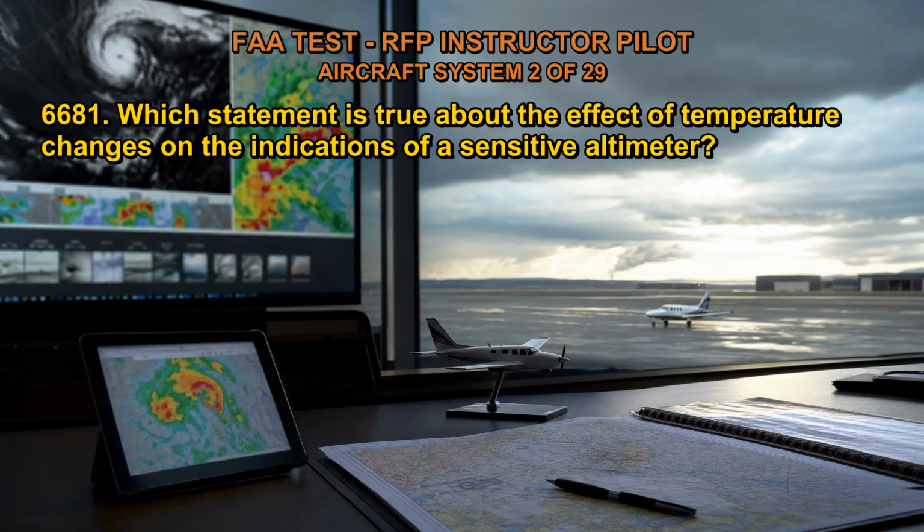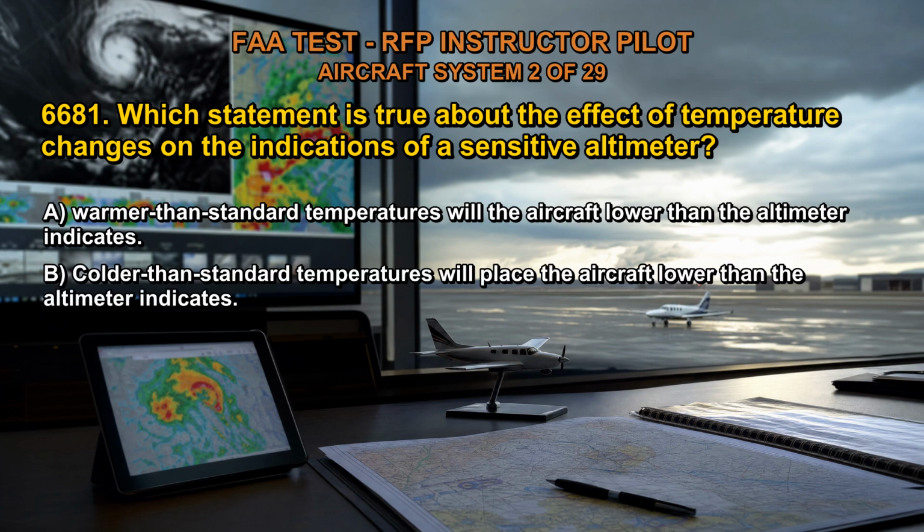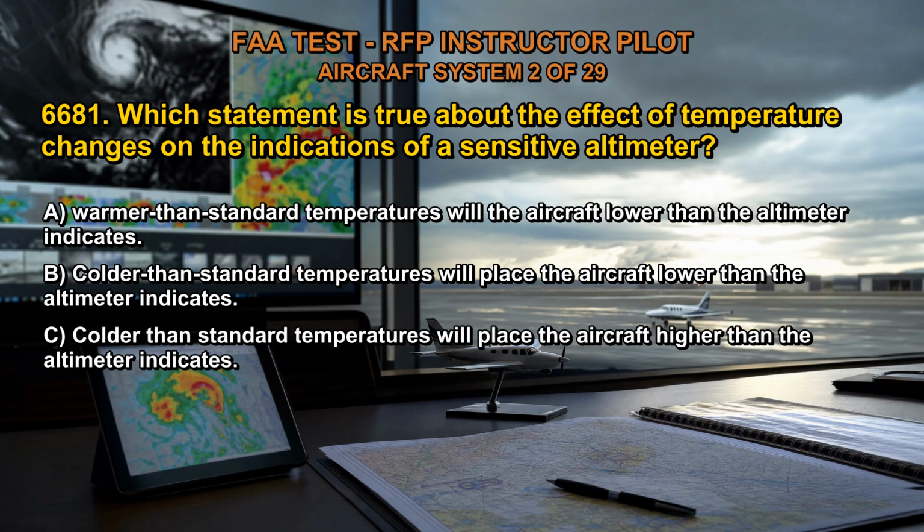6681. Which statement is true about the effect of temperature changes on the indications of a sensitive altimeter? A. Warmer than standard temperatures will place the aircraft lower than the altimeter indicates. B. Colder than standard temperatures will place the aircraft lower than the altimeter indicates. C. Colder than standard temperatures will place the aircraft higher than the altimeter indicates.